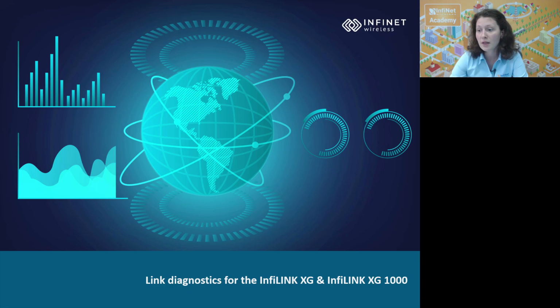We have no retries because the chipset does not support ARQ. When you see errors on XG, it always means uncorrected errors that will affect the data directly, as Nick is saying. Gerald Thomas is asking what he should do if the CINR is not above 30 dB.